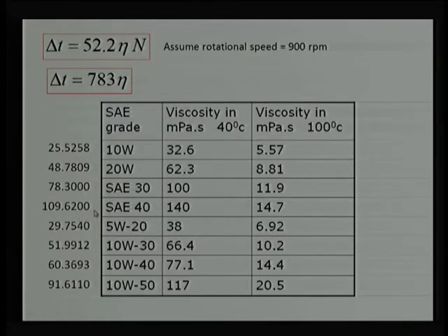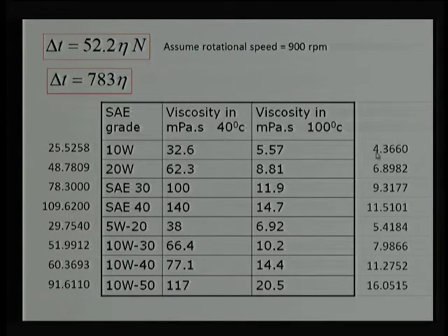during operation. However, if we account the actual temperature, say the temperature is 100° centigrade, and we try to figure out, based on that, the effect of this viscosity, what we get is the temperature rise only this much. That means T in we are assuming 100° centigrade, and when we count this viscosity, we find a temperature rise of only 4.3 or 4.4° centigrade.